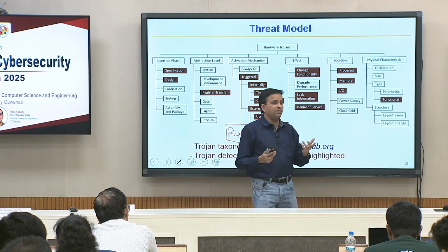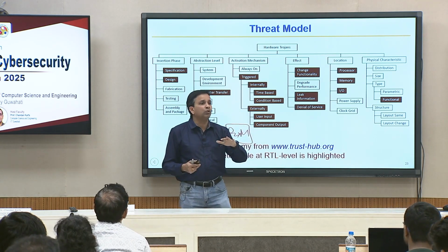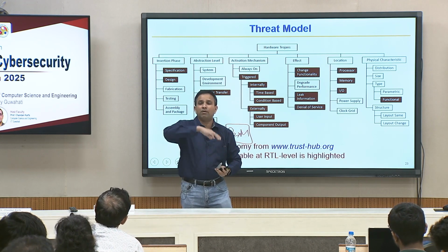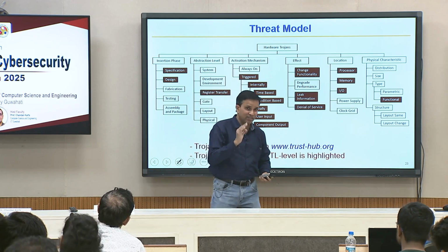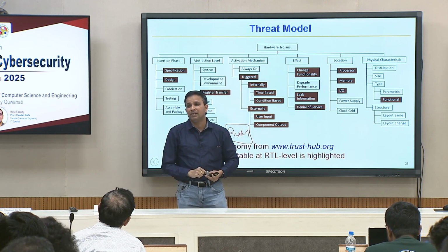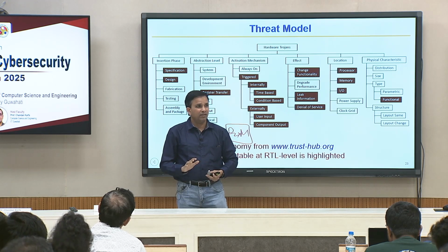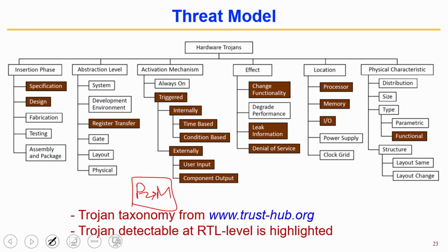Now, on the surface it may seem like, what difference does it make? It does, because a device comes with a cooling mechanism, with a limit on how much it can cool. If you suddenly increase the power profile and it becomes hot, every 10 degree centigrade change in temperature reduces the lifetime of the device by half. 10 degree centigrade, that is it. So, it can change the power behavior, and we can talk offline about how we do that. There is a notion of power virus, temperature virus, but whatever it is, it basically has that effect, right. Same thing about layout, violating a lot of layout conditions and all that.